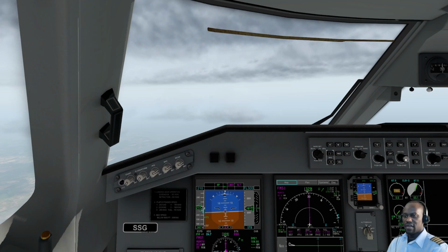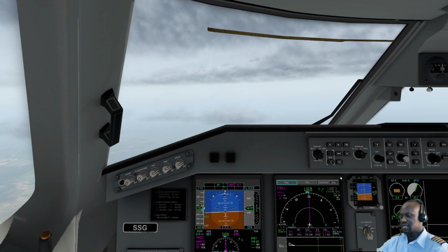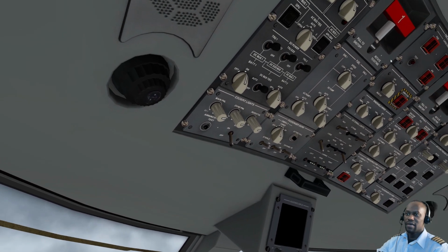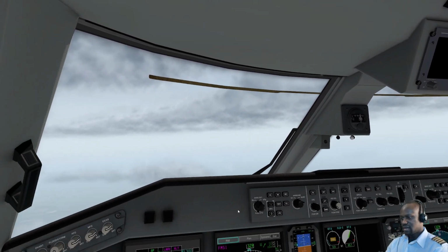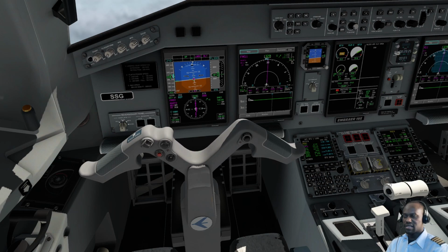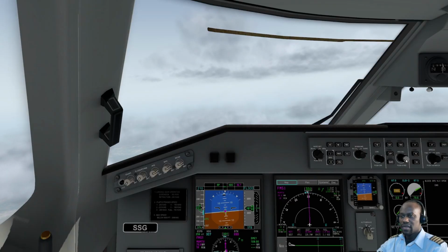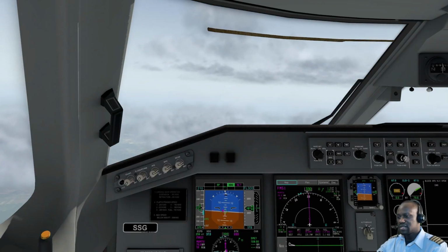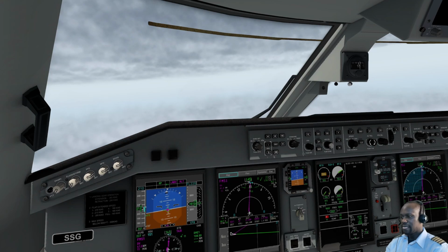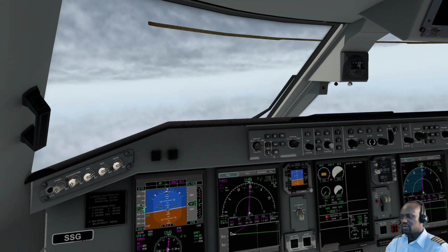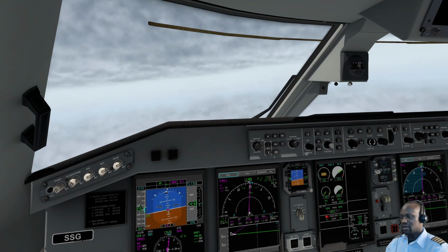The first thing that we're going to do in this case, since we've already determined from our diagnosis that it's a failed engine, I'll just go and start the APU. So starting the APU, so that we have at least two generators. Engine number 1, which has the fail icon, thrust lever idle. So engine number 1 starts up selector, stop, heading, and start my turn back to Dar es Salaam. Set 2,300 feet on the altitude window and commence a shallow descent.